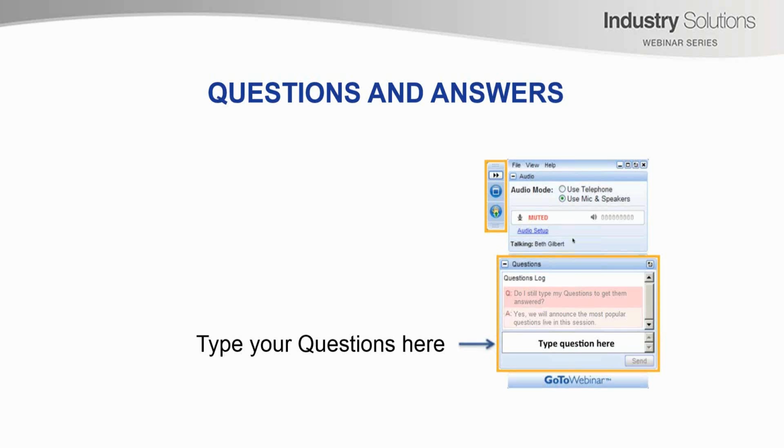I'll take this one, Rob. That's a really great question. It's particularly relevant for your urban assessments. And it's actually quite a complex question, although it doesn't sound it. As some background information, the TUFLOW engine uses the shallow water equations for its calculations. So as a rule of thumb, we'd like to advise people to not exceed a cell size to depth ratio of say 5 to 1.